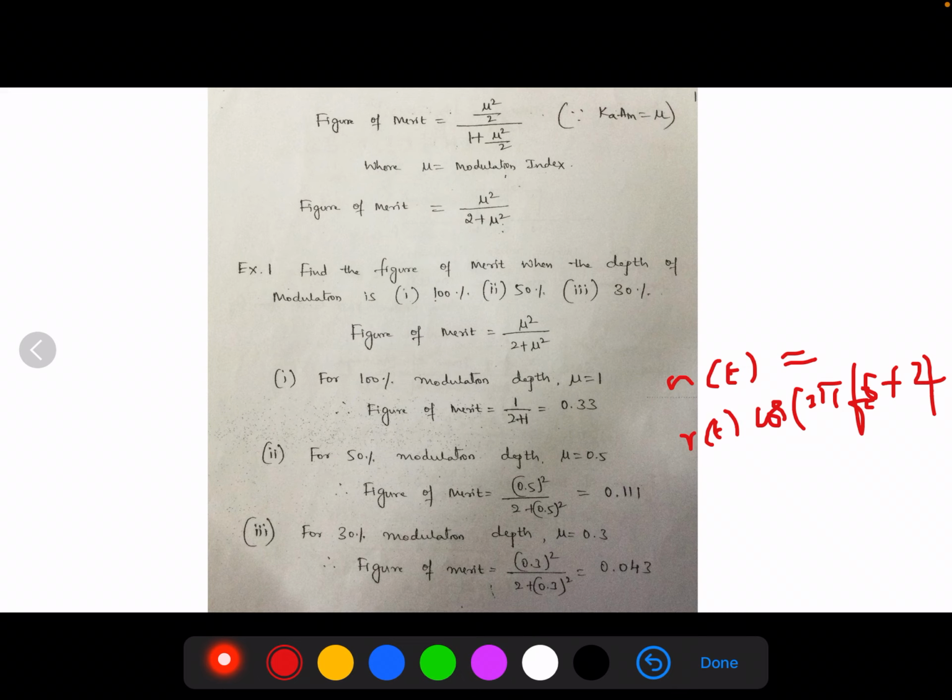So we can also recall that the phase psi of t of the narrowband noise n of t is uniformly distributed over 2 pi radians. So it follows that we have a complete loss of information, in that the detector output does not contain the message signal m of t at all. The loss of a message in an envelope detector that operates at a low carrier to noise ratio is referred to as the threshold effect.